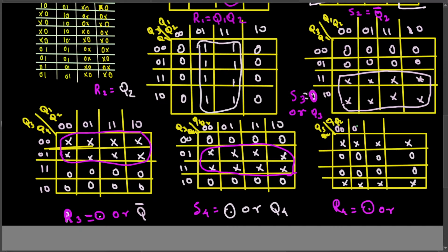This is the K-map with labels 0 0, 0 1, 1 1, 1 0 on each axis. I can combine this as 8: I take the top 4 and connect it with the bottom 4. In that way we make it 8. If we do that, what's changing and what's not changing? Q1 is changing, 0 to 1, eliminated. Q2 changing, 0 to 1, eliminated. Q3 is 0 here and 1 here, so changing, eliminated. Q4 is 0 0, not changing, so it's going to be there. Since Q4 is 0, we have to put a complement for it, and that's it.